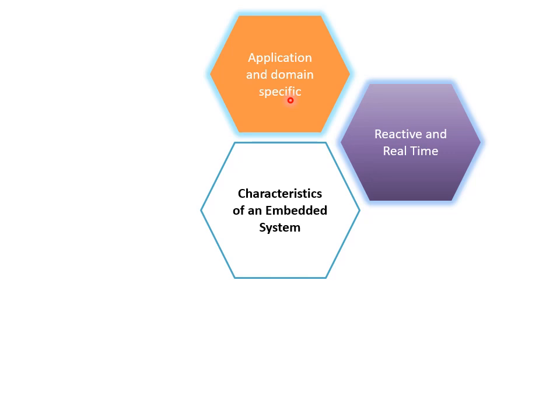That's why I say it should be real time also. It is reactive. My system is reacting. There is some event happening. My system is designed to know whether there is some rain outside. When rain comes, my system is detecting that. After detecting, what? For example, take a system in a modern car, where you have auto rain wipers. It detects rain and the wiper automatically switches on. So it is reactive. It should be reactive and real time. Your wiper cannot afford to switch on when there is no rain, and it cannot afford to switch on after some time of rain. It should happen at the desired time.